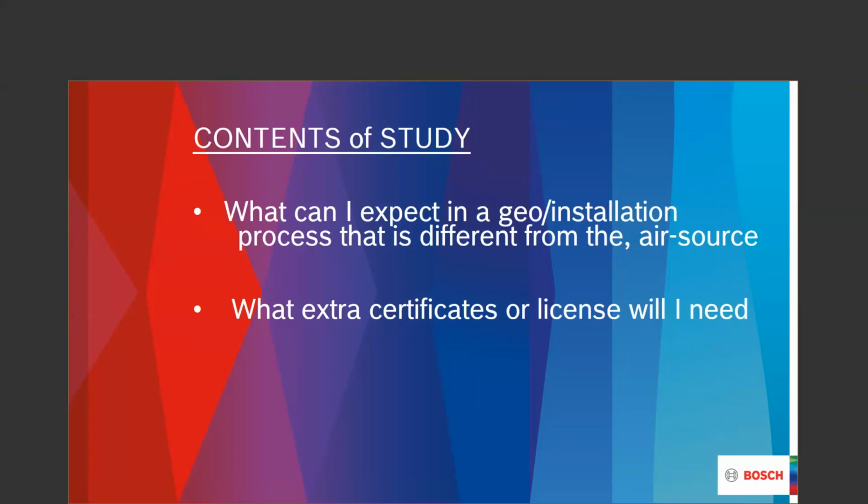Any time that you would go dig in somebody's backyard or side yard or wherever you're going to be, you're going to have to get some type of a location permit. You're going to have to find what's underneath that ground. Nobody with a backhoe or an excavator or a trencher is going to put that bucket, that chain in the ground until everything that can be located is located.